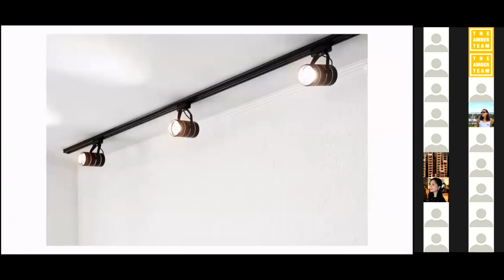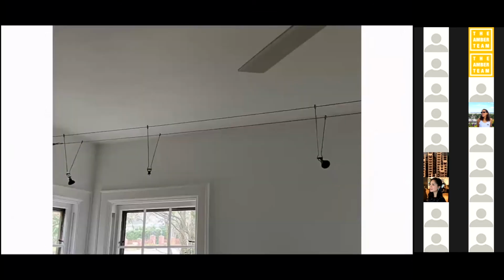And someone said this also in the chat, if we have outdoor lighting and we're afraid of a short, or people are going to be outside in a puddle futzing with a light, we want to make sure we're using low voltage. This is my house, and this is a cable track lighting, LEDs, and there's a transformer somewhere in the basement that takes that 120 volt. Remember, a transformer from last week steps down the power, in this case from 120 volts down to, say, 12 volts. I think this is a 12 volt system, maybe 24, but I think it's 12.